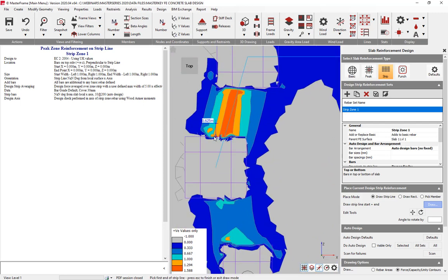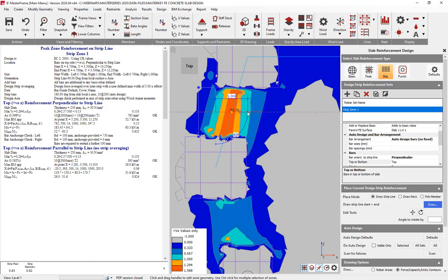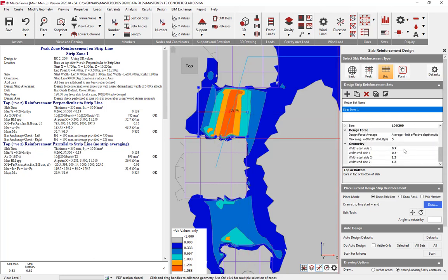Zoom right down in here, and let's just pick in the middle of that and go straight up. So I can control the scope of this by dragging it around, or indeed by coming in down here. We do actually have different dimensions. Instead of just 2 dimensions, you've got 4, so it can actually provision a varying bar range, if you like. So although this is placed like this, it actually could be arranged that it's all the bars of all the same length, but placed in a fashion where they're following more the profile of the wall.